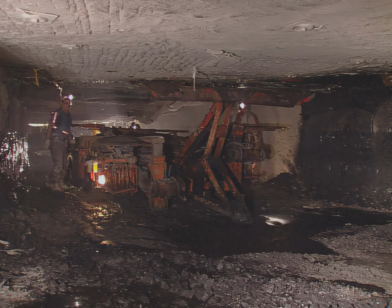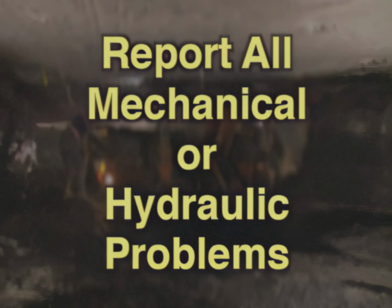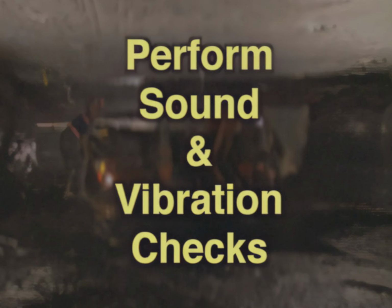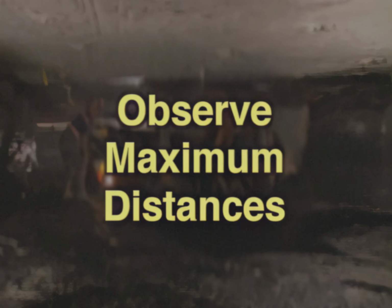ATRS is a great help. Do you know how to maximize the protection that an ATRS system can provide? Here's what you can do if you are a roof bolter. Report all mechanical or hydraulic problems with the ATRS system to your supervisor. Always make a thorough examination of roof and ribs before doing any work. Perform sound and vibration checks. Follow the bolt installation sequence in your mine's roof control plan. Following the approved bolting sequence is extremely critical when operating a single boom roof bolting machine. Observe the maximum distance that an ATRS system can be set beyond the last row of bolts as listed in the roof control plan.